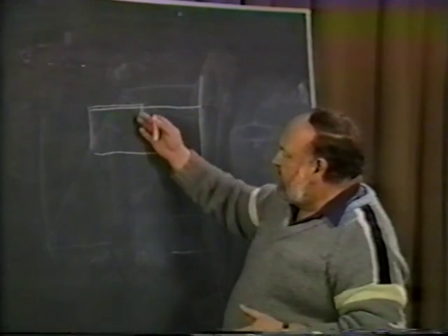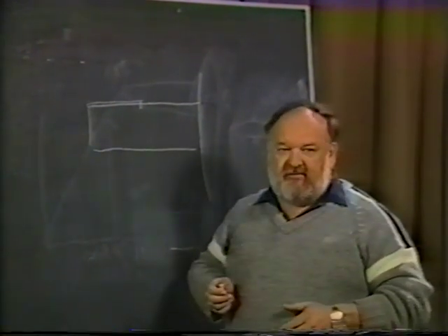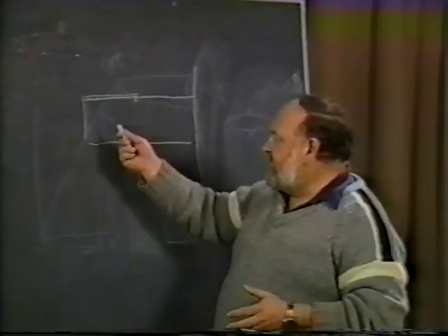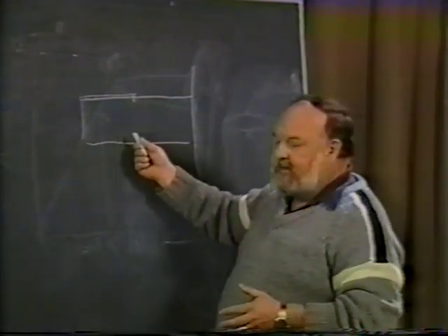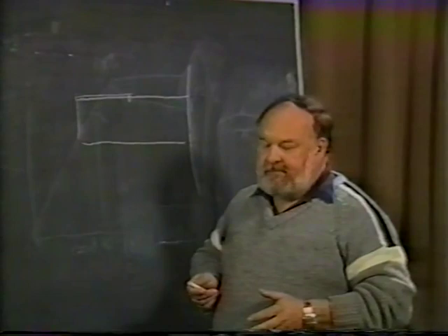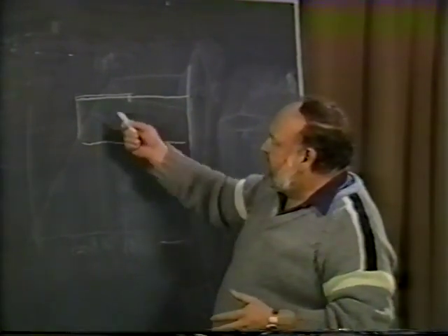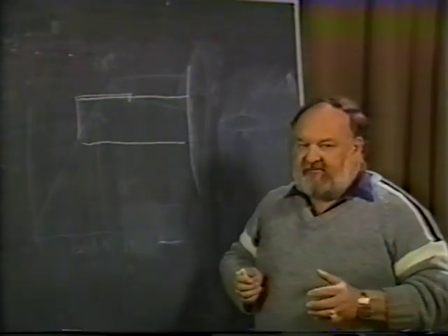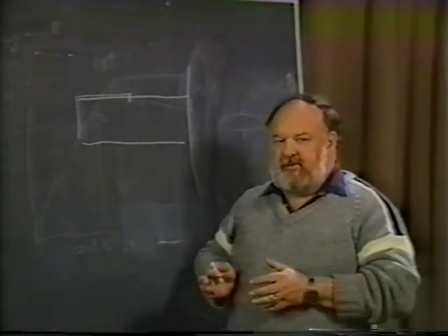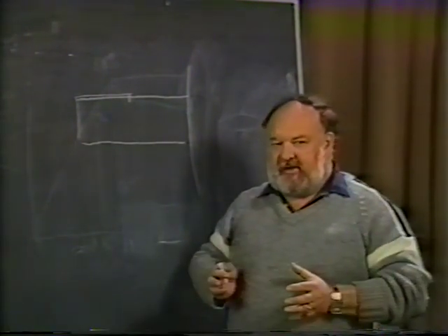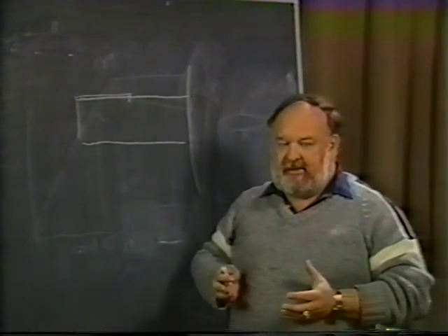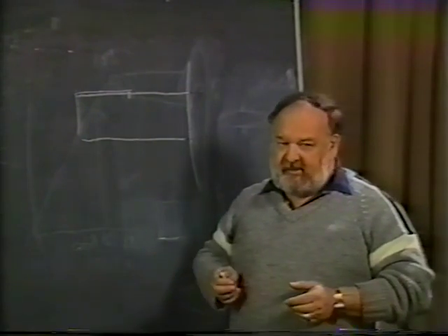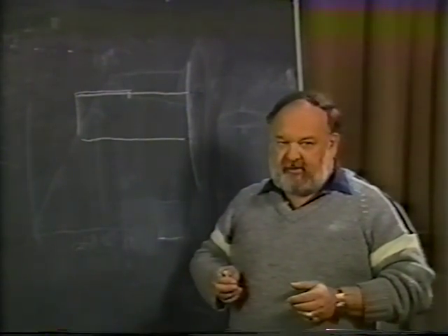And one of the reasons was that this portion of the wing itself was not stalling, was not separated, or was considerably less separated once it got into a full spin as compared to the inboard section. How this is done, you've got to watch very carefully. If you're not concerned about the cruising condition of the airplane, then you can put these big cuffs or big leading edge radiuses on it, which will give you good low speed characteristics, but one of the disadvantages is it does create a fair amount of drag once you're cruising along.